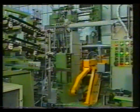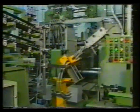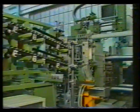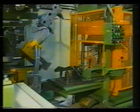Insertion of the lamination stacks, extraction of the cast rotors, and die spraying are all done at the same time. During spraying of the fixed die half, the rotors are extracted from the movable die half. When the lamination stacks are inserted in the fixed die half, the movable die half is sprayed. The cast rotors are placed onto the lower part of the trimming die.